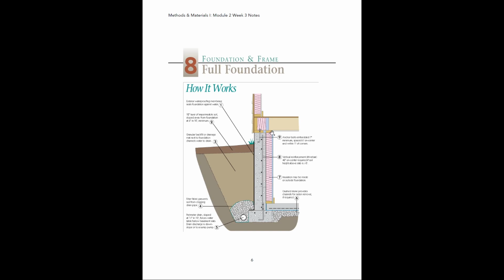They will actually build a wall in front of the concrete wall right here, and you can see this wall is insulated. They have a baseboard and stuff on it, and then it looks like a drywall ceiling. But then on top of that, we have our superstructure, okay? And the superstructure is going to be bolted directly into this concrete or CMU or whatever it is that the foundation is made of, okay?